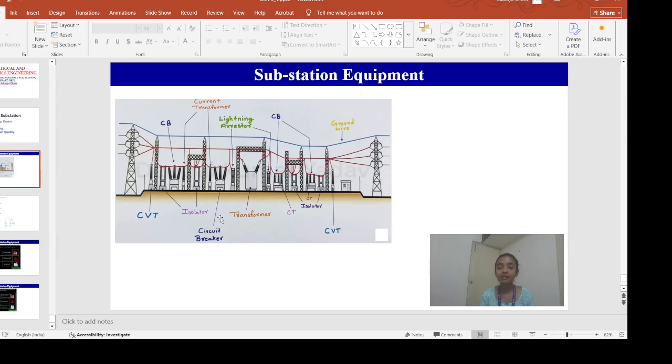Okay, but making the current zero is not enough. Suppose there is some fault in the transformer, and you want to have maintenance on the transformer. When the electrician comes, first he will make sure the current is zero through the circuit breaker, but that won't provide you the 100% guarantee that all the supply is off.